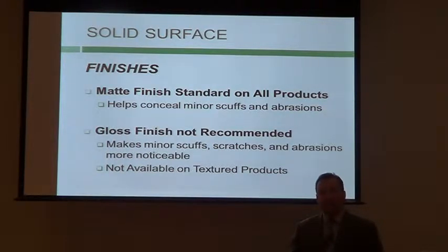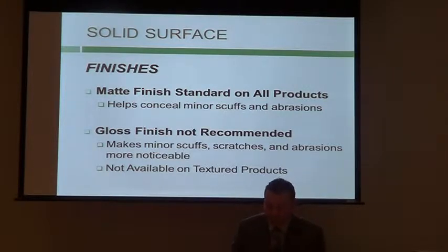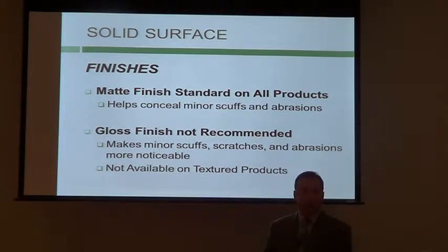And unfortunately, the problem with the polished surface and solid surface, remember I said earlier, it's about a 5.5 on the Mohs hardness scale. The number one culprit against, quote unquote, I just destroyed my countertop, is the end user. Could be a homeowner, could be somebody in the cleaning staff of the building, takes something a little too aggressive, and they apply their thumb or their two fingers to scrub something away. If I have a polished surface, I guarantee they just dulled it there. And now they're scratching their head, they think they destroyed their new surface. How do they bring that back up to a uniform finish?